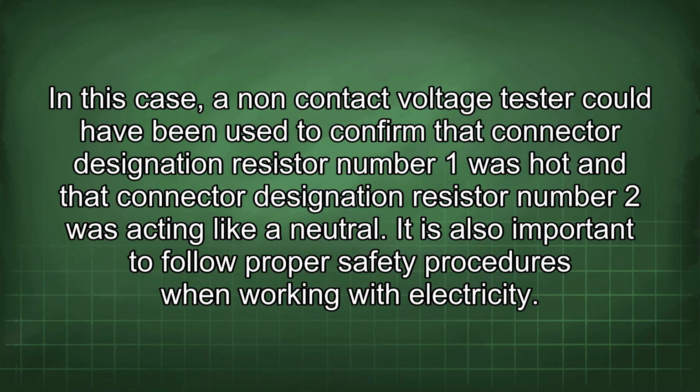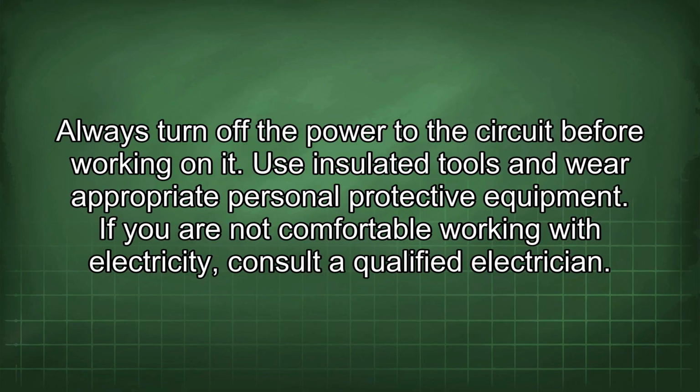It is also important to follow proper safety procedures when working with electricity. Always turn off the power to the circuit before working on it. Use insulated tools and wear appropriate personal protective equipment. If you are not comfortable working with electricity, consult a qualified electrician.